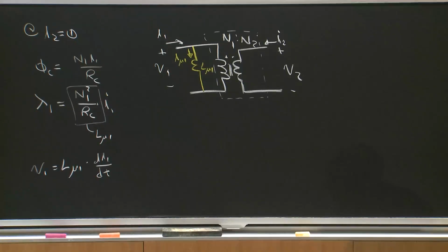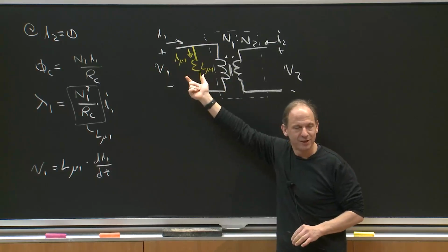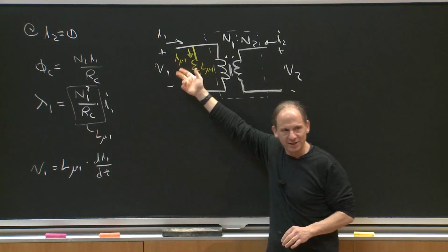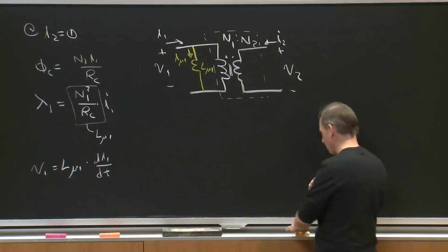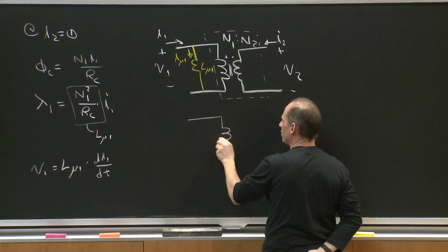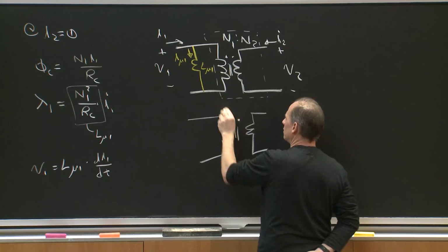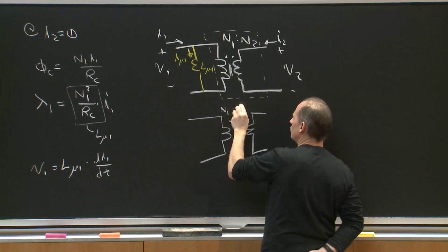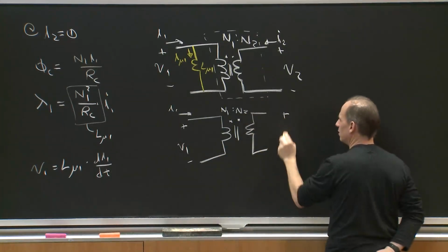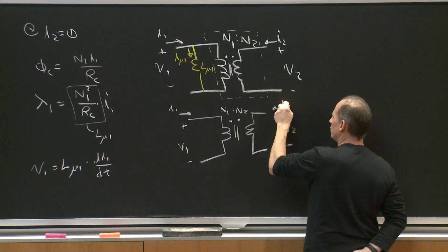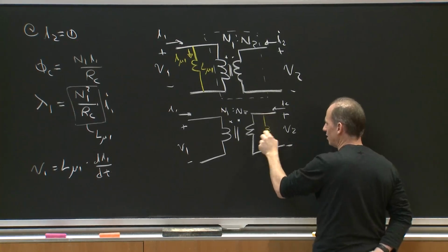Okay. By the way, I put this on the primary side, in the V1 I1 side, as opposed to the so-called secondary side, the V2 I2 side. I could have done it the other way, right? I could have modeled the transformer equally like this, N1 to N2, and had V1, I1, V2, I2, and I could have placed my magnetizing element on this side.